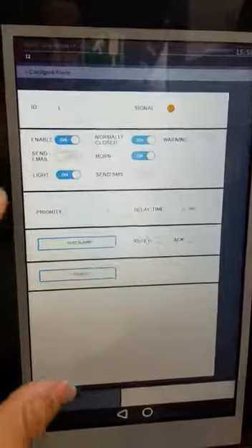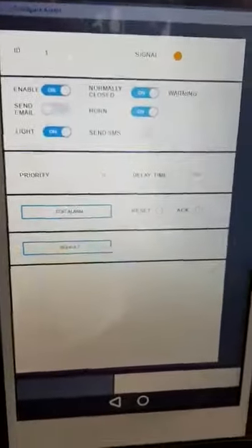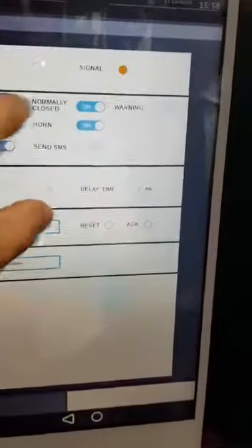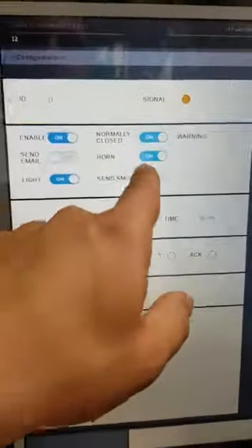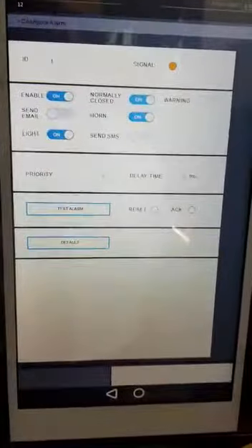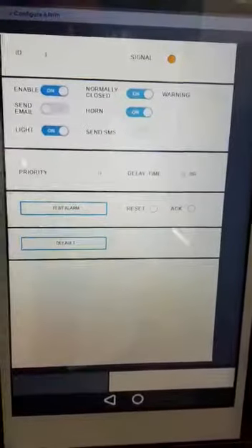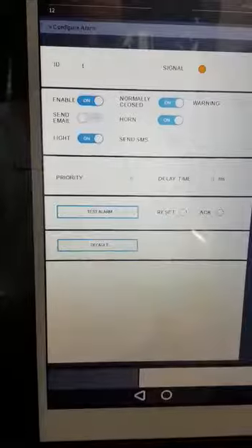It'll basically give you a full test of what the emergency, like for example, the emergency stop is pressed. It'll tell you, okay, we can check the contacts if they're normally closed or normally open. Probably the horn's not working on the emergency stop. Could be very simple. Put it on, put it off. So we're basically sending a direct signal to that input or output. And again, the other feature being so far away is the remote possibility of us giving you service and support if this machine gets sent, you know, in Ayers Rock.